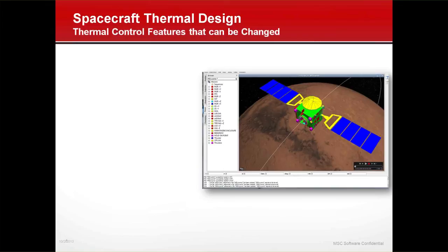When we talk about spacecraft thermal design, there are several things that we can use to control the environment of our spacecraft. You have things like batteries and electronic equipment that are temperature sensitive. Batteries, typically you don't want to get down below 5 degrees C or something, and electronic equipment may go colder than that, but you can get it so cold that you can damage electronics or batteries very easily. So we put heaters sometimes on spacecraft when the sun's not shining or when it's in an eclipse, and we use thermostats to turn heaters on and off, either proportional or bimetallic on-off.